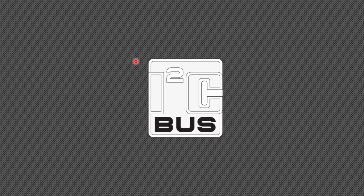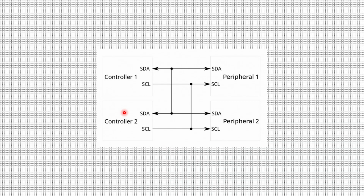So this is the most commonly used interface, the IIC, or you can call it I2C. So this is the inter-integrated circuit bus. So basically this whole thing works on serial data and serial clock connected to the controller and the peripheral. So each controller and the peripheral have these common connections between them. So the interconnected ICs can be toggled using the same data and same frequency. So this is the working.